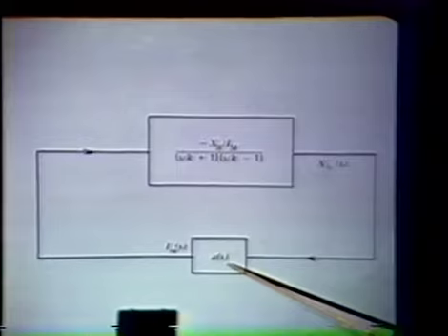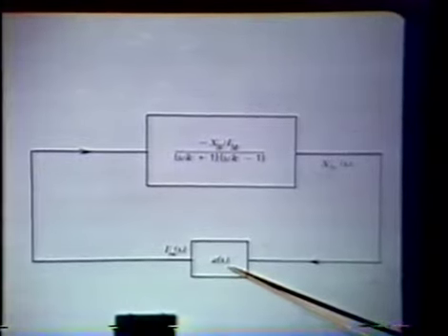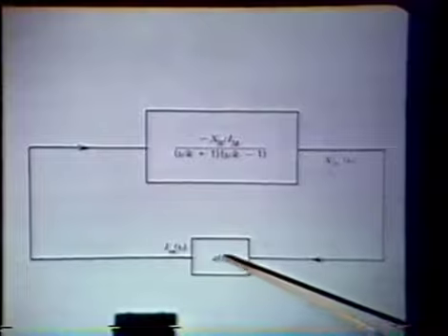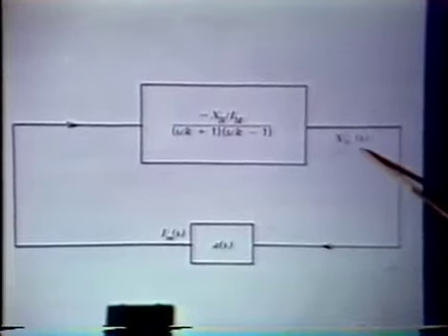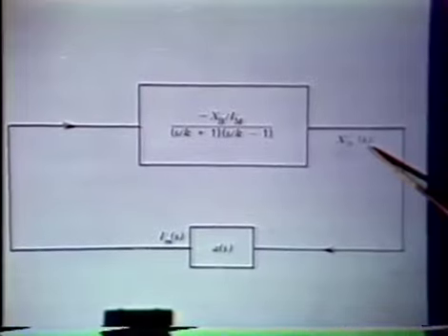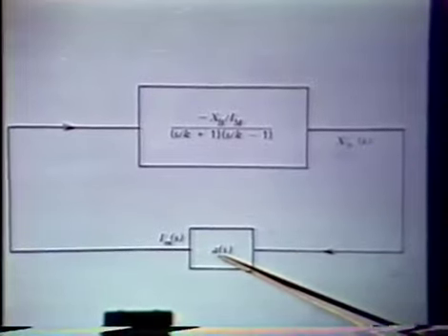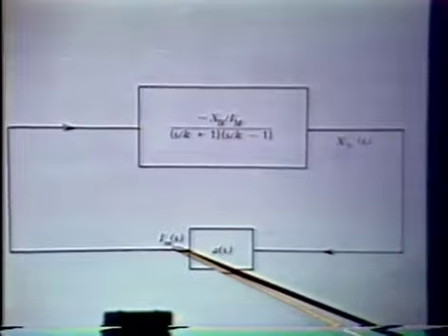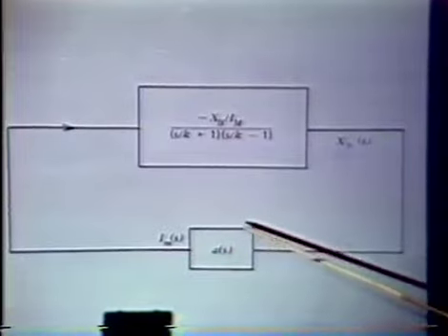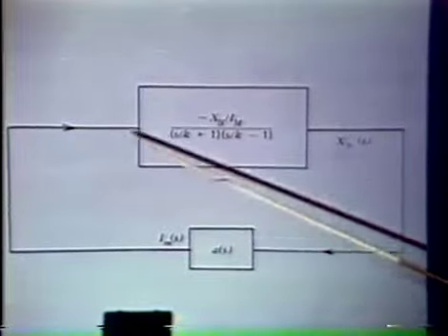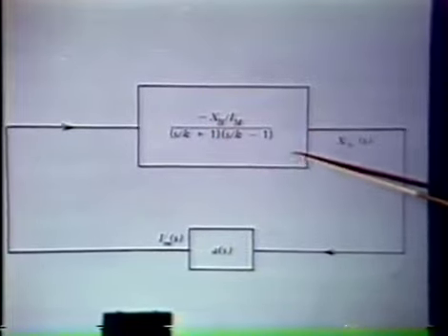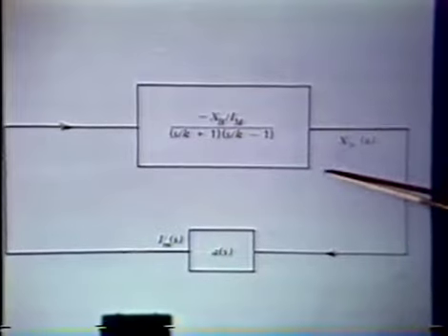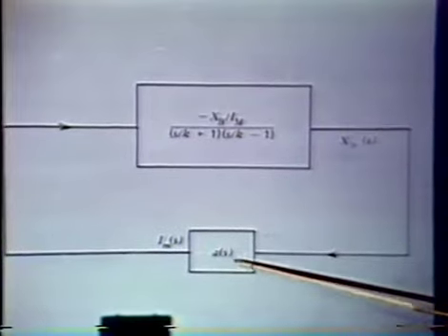We'll find out that we have to add some compensation. We take an amplifier with some dynamics, and we operate on the electrical signal proportional to ball position, and the output of the amplifier is magnet current. So this completes our overall loop. We complete the loop by surrounding the ball dynamics with our amplifier.